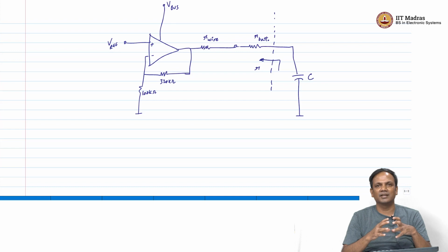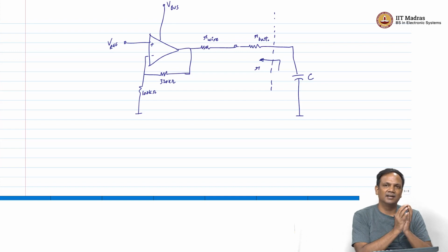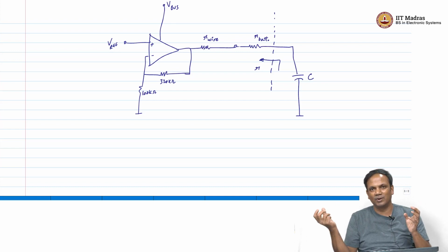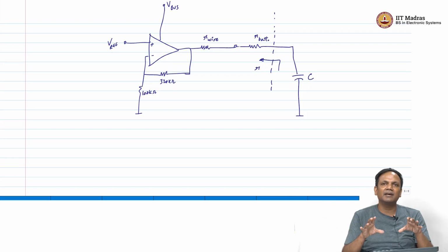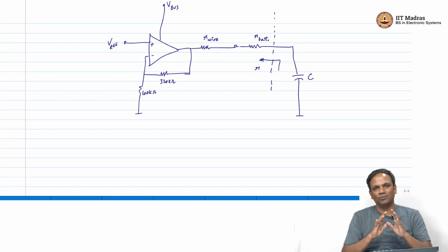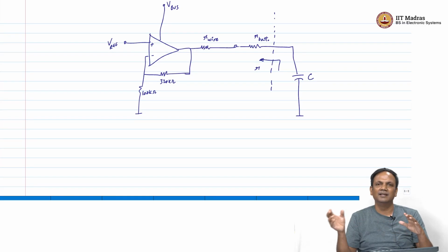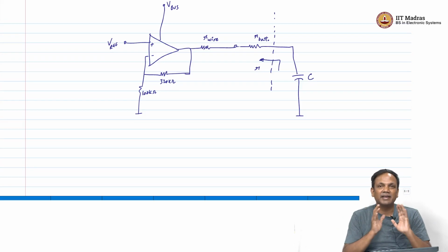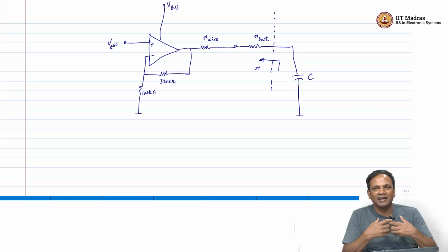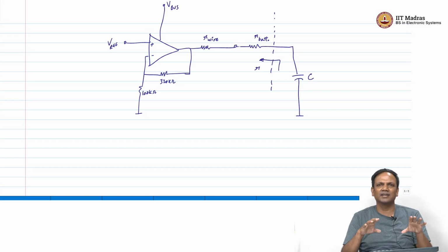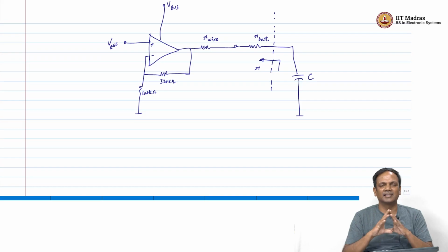So, a 1000 mAh battery, that 1000 mAh is called 1C, and typically they advise you to charge the battery at rates no greater than 1C. In some cases exceptions are made, but the general advice, unless you spent extra on the type of battery with special protection circuits, is to limit yourself to 1C charging. That will give you good aging characteristics for the battery.